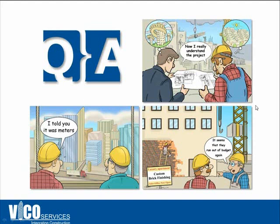That's a very good question. You can actually create those templates, yes. First of all, you can capture inside the Vico 5D environment and standardize all the tasks and their production rates and an assumption on crew sizes. And that will help you generate a schedule automatically based on just inserting the design or linking it to the design BIM model.